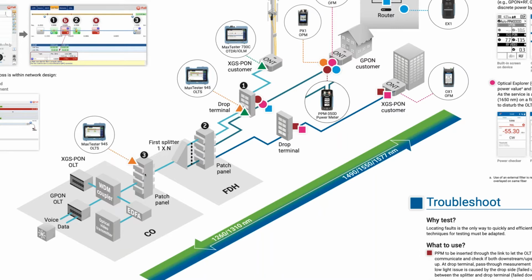You can obviously connect that to the OLT and just test with a power meter to confirm that you have light at all of the ports coming out of the splitter. But what I would suggest, and I think is a better use of the equipment that may be available to you, is to test the entire length from the CO to the splitter. Make sure that that link is sufficient, and then test from the splitter out to the drop with your OTDR.